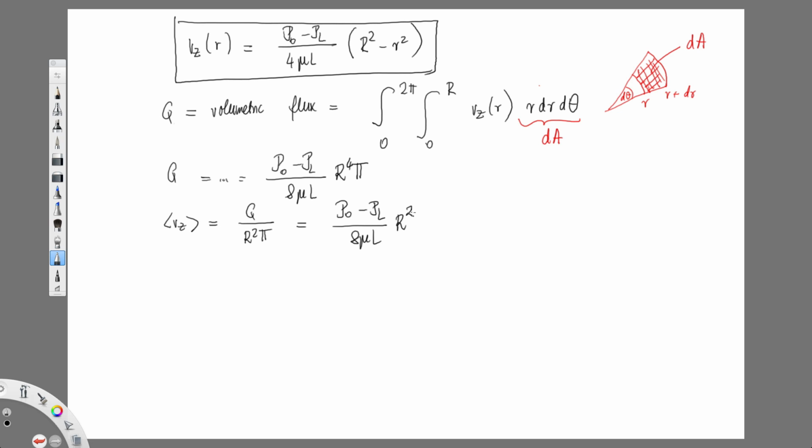Newtonian fluid comes into play when I'm actually solving for velocity profile. So technically that tau rz expression is valid for your toothpaste, which is not a Newtonian fluid. You have to squeeze to get it out. The moment you have to squeeze the fluid to get it out, it's not Newtonian. So it's actually a yield stress fluid. So basically the general form would be fine in a cylinder, and it would be fine in an annulus as well.